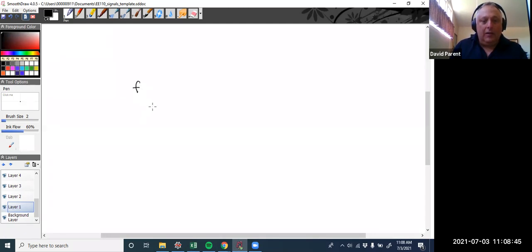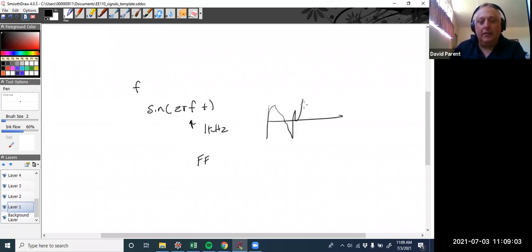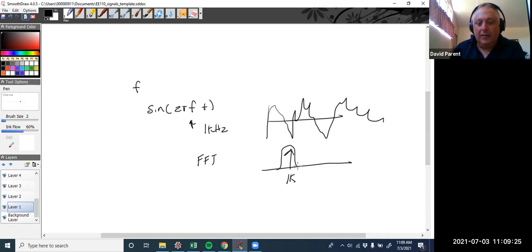if we want to detect a sine wave, and that's a kilohertz, you might say to yourself, well, if you had this signal with a sine wave in there and you want to find it, just take the FFT, and hopefully you'd find that there was a 1 kilohertz sine wave there. And you might think, well, let me just put a bandpass filter around it, right? But sometimes the amplitude is too small for the noise that's there, all right?